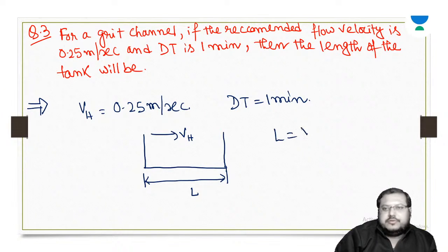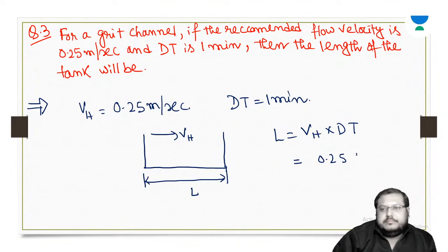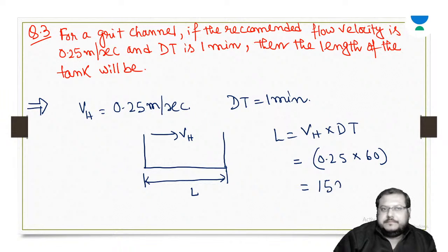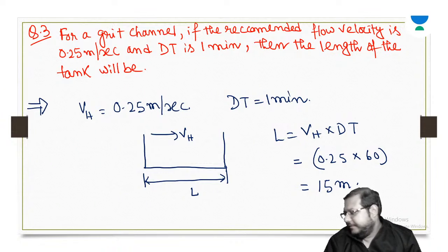So L is equal to VH into detention time, 0.25 into 60. It's 15 meter.